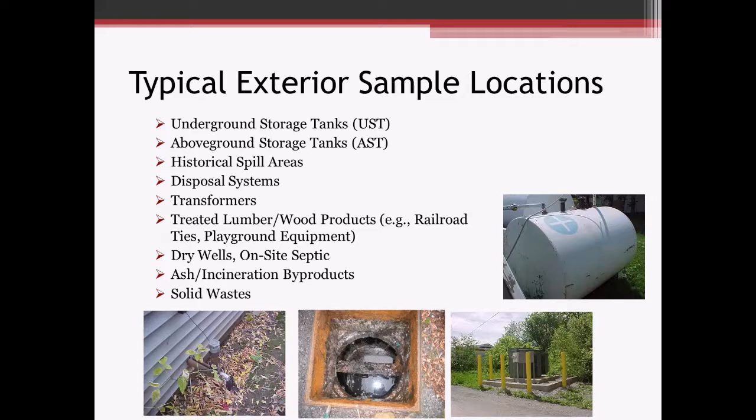Dry wells, basically a hole in the ground where they fill it with gravel or some other media and they discharge drains to it. A lot of times those are not allowed anymore, depending on the drainage situation. Floor drains going into a dry well isn't something that's allowed anymore, and oftentimes would be a receptor of contaminant. So you want to make sure you don't have any of those, and dig them up and close them out if you do. Septic systems, ash, incineration byproducts, the hazards that might be associated with burying partially combusted materials could present some contamination issues.